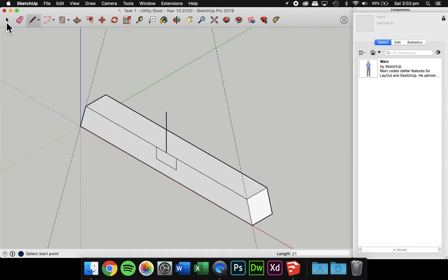and if I go back to my 3D view, Command 7, that's what I've got. This line here is no longer needed, so I can delete it. And we're now going to use our push-pull to cut this section away. So click on it, drag it backwards, and you've now cut away that shape. So you should see that we're making really good progress now on this bottom rail. The only thing that we need to do is work on the two ends.